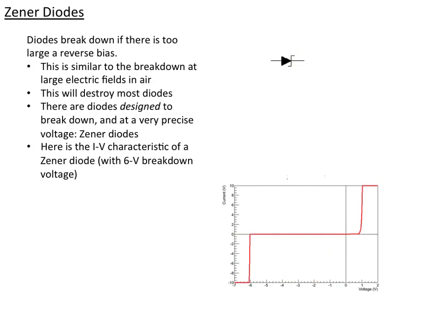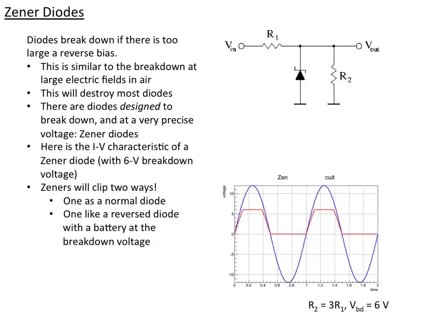for the Zener. And so here I've drawn the IV characteristic for a Zener diode in the normal way, plus and minus on the voltage drop, and if we put a large negative voltage, eventually, at something like 6 volts, we get a very sharp cutoff. Notice this cutoff is much sharper than the turn on of the regular diode. So the breakdown voltage works very much like a regular diode drop, but it cuts off at different values.